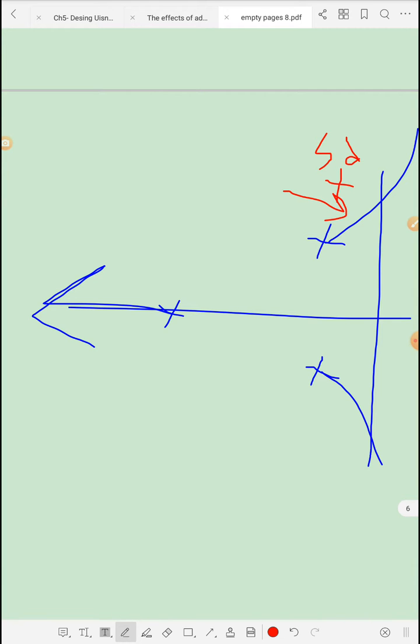So in this case, gain adjustment will not solve our design problem, because the root locus is not passing through SD, and at SD the value of the angle condition is not odd multiples of 180. In this case, we should add poles and zeros to the loop transfer function or the original plant in order to reshape